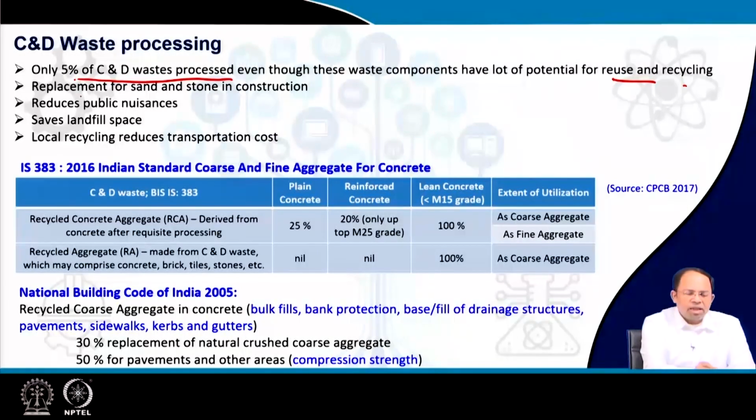And it acts as a replacement for sand and stone in construction. As you have seen earlier, for structural concrete, it's better not to use this kind of processed aggregate, but for non-structural concrete, for lean concrete, it's fine. We can use this kind of material.